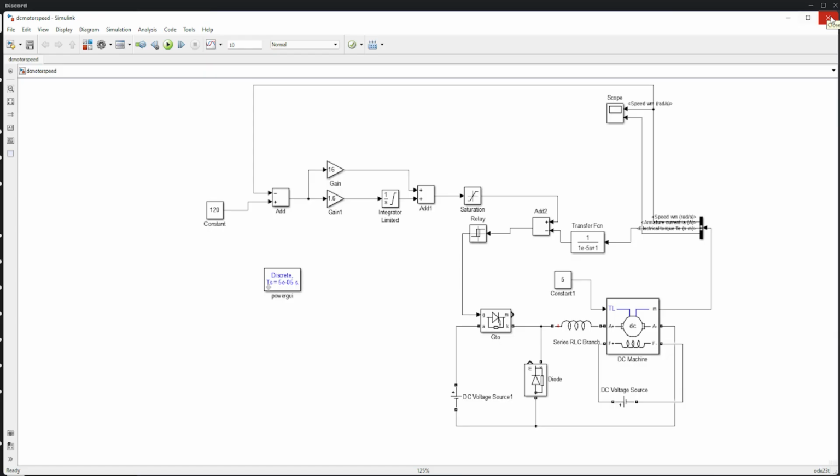Hello, this Simulink model is of a speed control loop of a chopper-fed DC motor. The various blocks in the Simulink model shown are chopper-fed DC motor, thyristor, constant value block, add, gain, diode, etc. In this model, there are various blocks that form a group signifying a certain function. The thyristor, diode, GTO, inductor, voltage source form a chopper. Chopper is a static power electronic device.